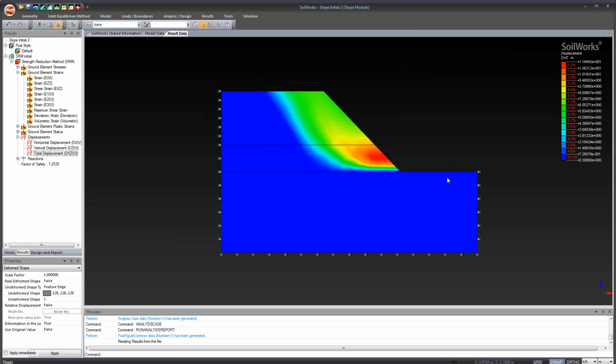So now, based on this, as I already showed you in the presentation, the first analysis gives you an idea of where exactly your model is failing, okay, and what is the length of the reinforcement you can consider, okay, and which area needs to be more dense. For example, in this particular one, you can see that the red area is displacing more than the rest. So you can increase the intensity or the number of nails over here rather than going to the top of the nails.